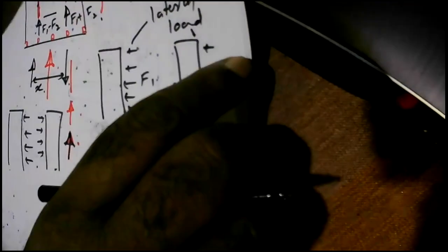So because of that reason, the individual elements are not going to resist any torsion, and not even the shear wall is going to resist torsion. Only shear walls that will resist torsion will be the shear wall assemblies. So if you have a shear wall arranged this way, then this kind of assembly which is closed with a beam can resist torsion. Otherwise, all the torsion will be resisted by individual elements. Is that clear? Yes, sir. Clear. Thank you.